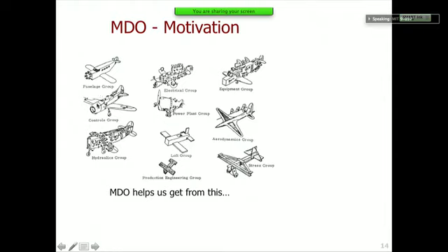The controls group is all about controllability, so you see the flight control surfaces are very big. The problem is these control linkages are on the outside, which is really bad for aerodynamics. But the controls people say, I don't care about drag, I'm making sure my control surfaces are deflecting appropriately.